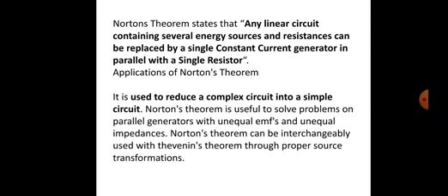Applications of Norton's theorem. It is used to reduce a complex circuit into a simple circuit. Norton's theorem is useful to solve problems on parallel generators with unequal EMFs and unequal impedance. Norton's theorem can be interchangeably used with Thevenin's theorem through proper source transformations.